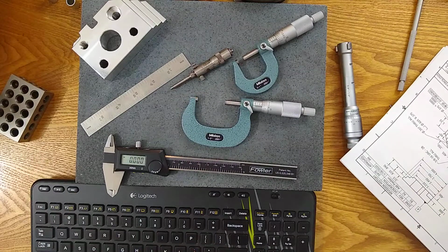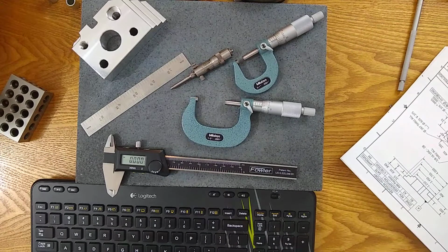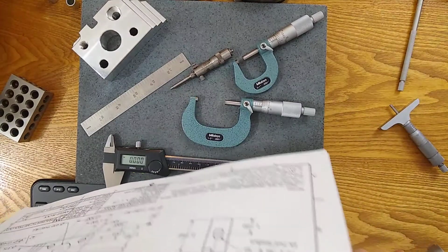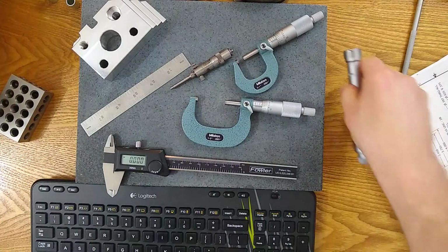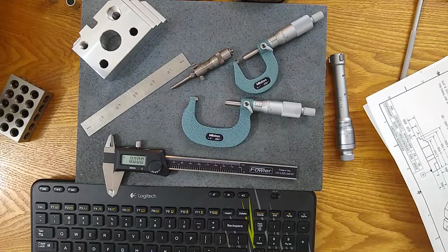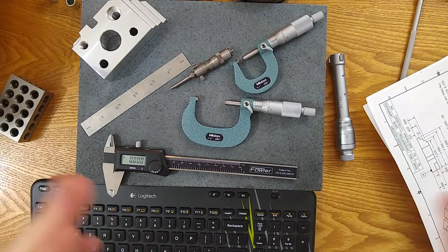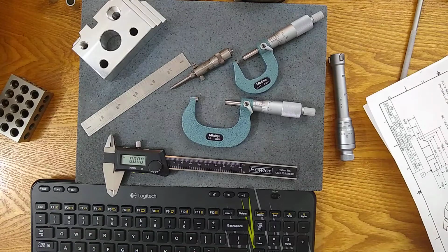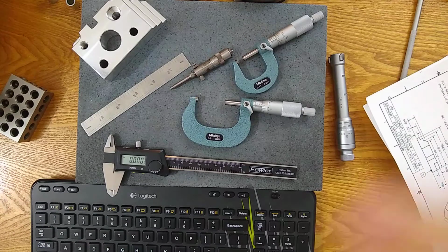You can certainly get very specific with your resolution and your accuracy down to the exact gauge you're purchasing. But these are some general industry trends I've seen comparing the manufacturers. And for years, I've had to purchase this equipment, and I've been checking out their resolutions and their accuracies to make the decisions that I need to inspect the parts that I have. And so, generally speaking, you have your calipers, your dial bore gauges, height gauges, indicators, drop, and test. They have variations in resolution, accuracy, and so that'll help you.